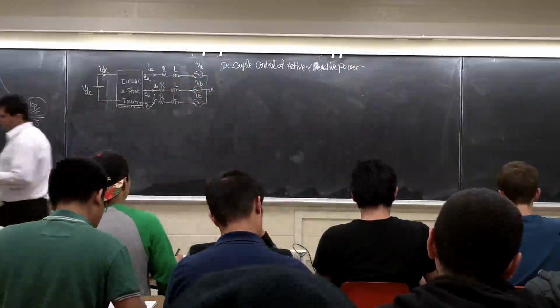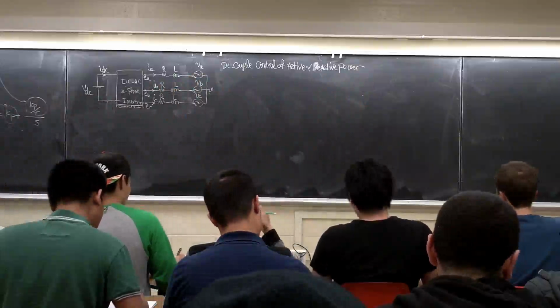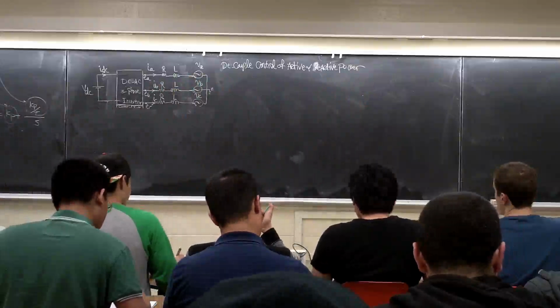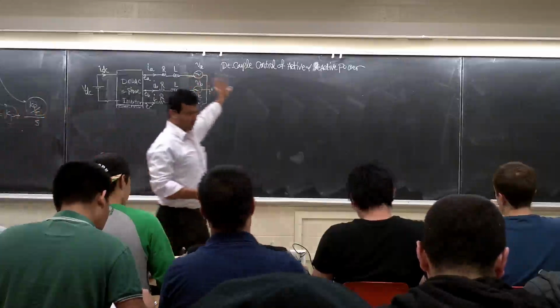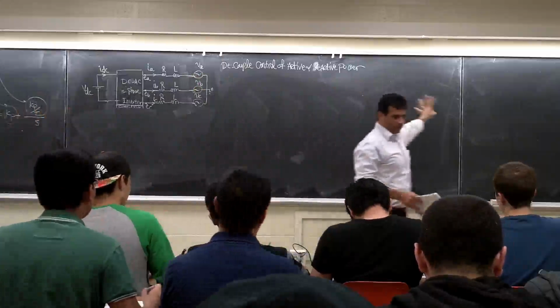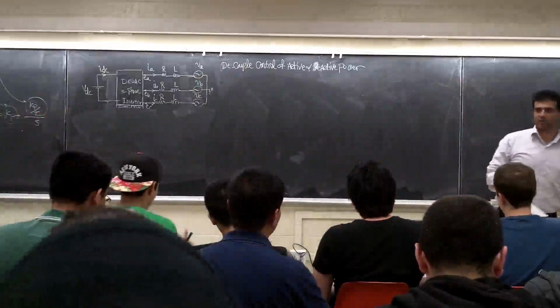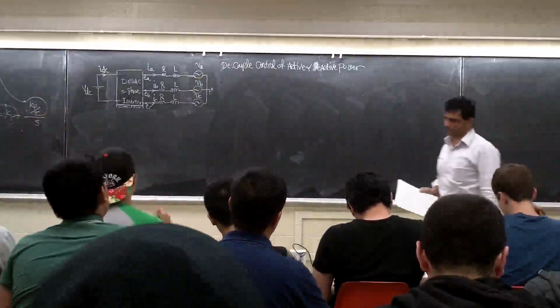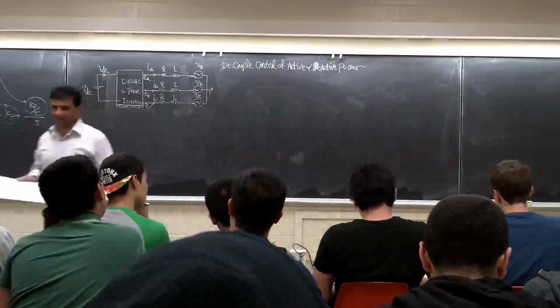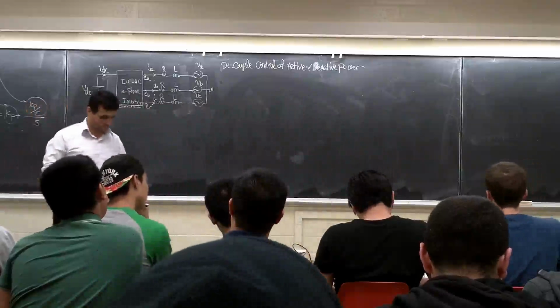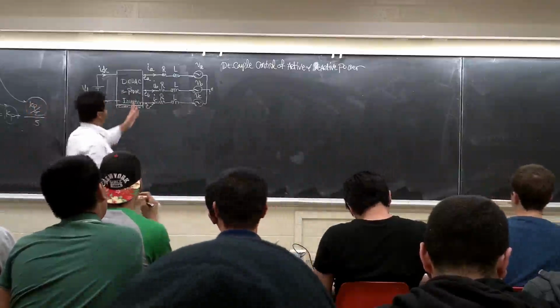It is usually used for AC motor control, like synchronous machines and induction machines. But because it's very similar, you don't know about that yet, but it's very similar to that one. They call this one also vector control. If you hear about the vector control of the inverter, it's the same thing: decoupled control of active and reactive power. Now let's start from here. Forget this part.